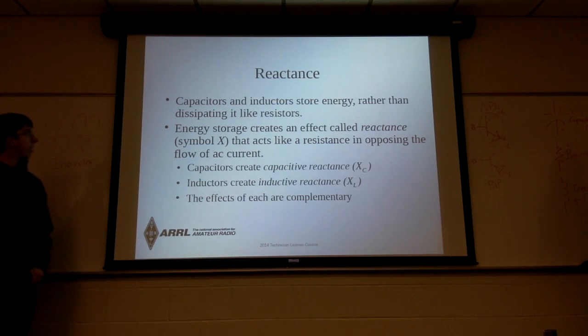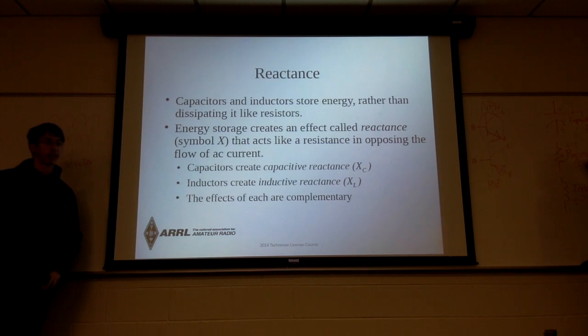All right, so let's talk about reactance. Reactance is like resistance in that it can limit the current and develop voltage across it. However, we talk about reactance for inductors and capacitors. When you charge up a capacitor initially, you see a lot of current, which gradually decreases, whereas an inductor, you see very little current and gradually increases. How fast they decrease or increase is related to the reactance.